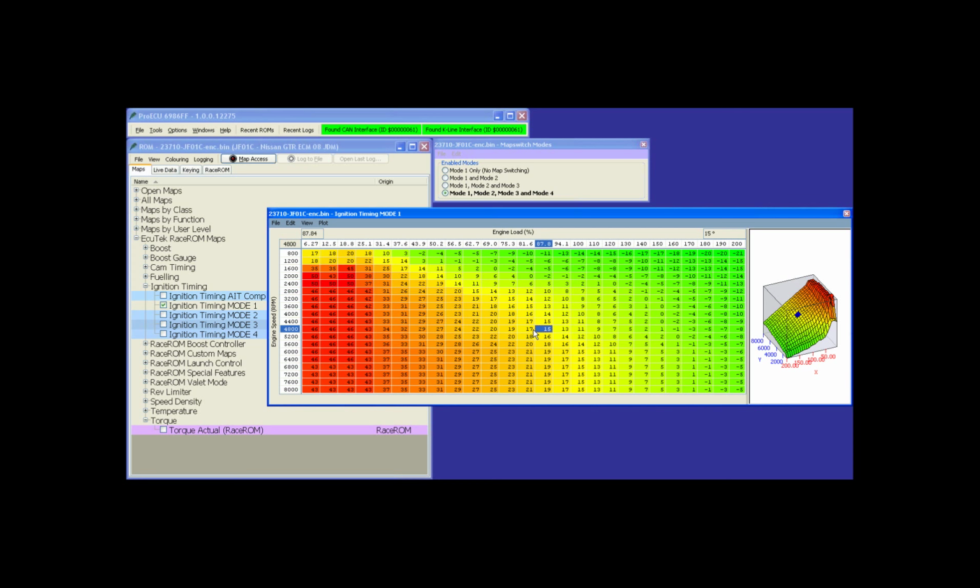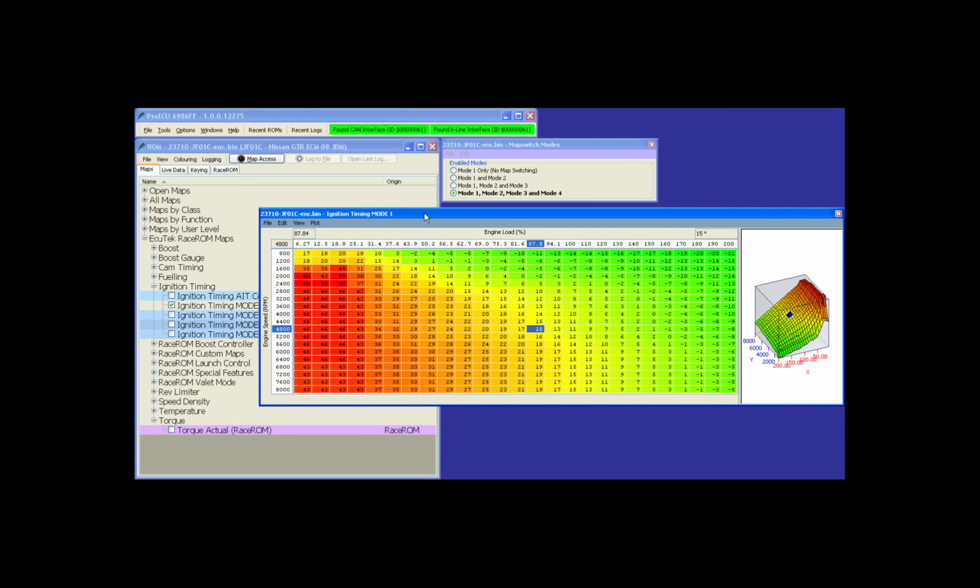They've been calibrated pretty much against a stock car, and from tuning, typically for the engine load that you achieve and the ignition timing values you're going to get, but they're not going to compensate for things like poor fuel, hot climates, and premium markets like Japan, where they've got high octane fuel and the car's going to take more advance. So you will have to calibrate these tables as per your local conditions, as always. Because this particular ROM is a JDM ROM, it would typically have more advance than something like a US ROM file running in hot conditions, altitude, poor fuel quality.